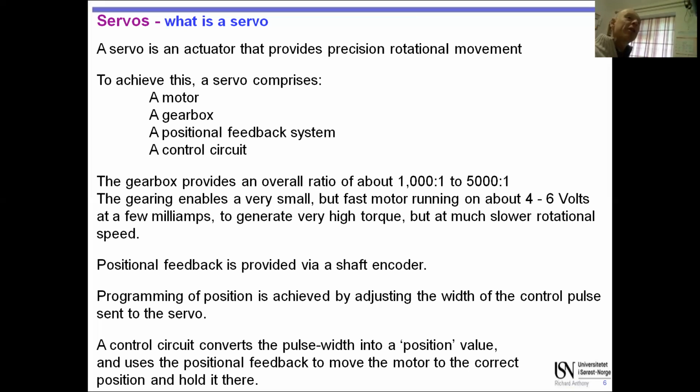If you're buying a cheap servo for maybe anything less than 200 krona, for example, then it's probably done like that. If you're putting a really expensive servo in a really big industrial robot, it probably will be an optical shaft encoder. Some of those servos are many thousands of krona, and they are a different level of precision to the ones that you have in small devices, in cameras.